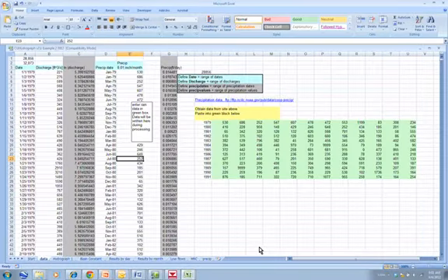To start off with, go to the Data tab, and when you're first using the program, you would put data in these columns here. The hydrograph data themselves go here in a date and flow format. The date is every day, and the flow is in cubic feet per second, the average daily flow for that particular day. This column is the log of the flows, and if it's gray, and in general, don't edit any of the gray columns.